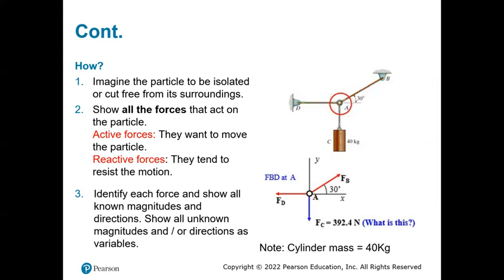First, at the edge of A, because there is a cable, I know that there's going to be a tension. Both are equal, pulling on it. So that I have the tension. And because of C I have the force downwards, 40 kilograms. Then I know all the forces.